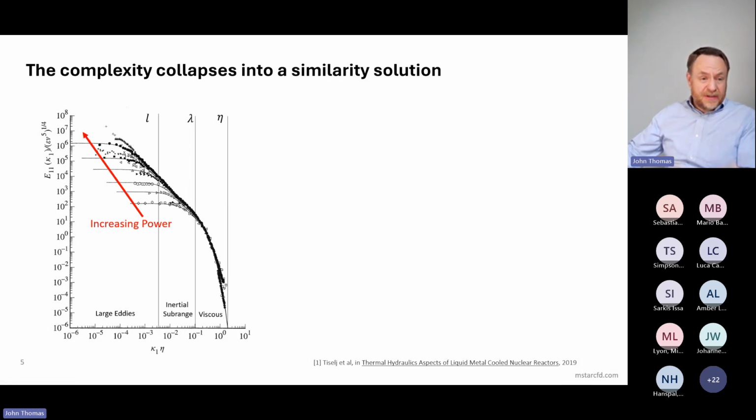It doesn't care what the impeller type is. It doesn't care if it's a nozzle. It doesn't care what it is. All it knows is that the Kolmogorov length scale is informed by fluid mechanics, regardless of the topology driving the turbulence. And so if we anchor the Kolmogorov scale, all turbulence collapses onto the self-similar solution. The Taylor scale as well is going to be related to Reynolds number. Again, it's an anchor that delineates the inertial subrange anisotropic eddies from the isotropic energy dissipating eddies as they go through this viscous dissipation regime.